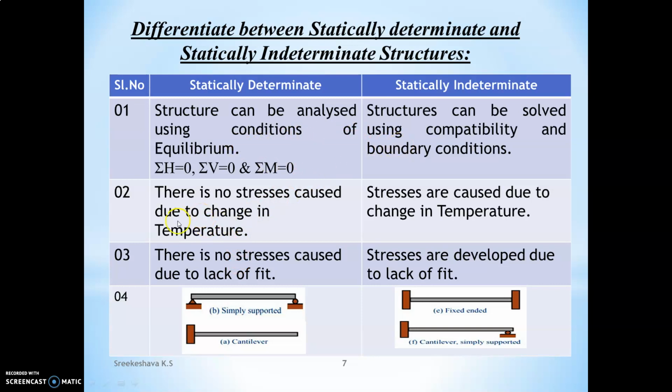Okay, the second difference is that no stresses are caused due to changing temperature in the case of statically determinate structures. Stresses are developed due to temperature in the case of statically indeterminate structures. No stresses are caused due to lack of fit in statically determinate structures. Stresses are developed due to lack of fit in statically indeterminate structures.